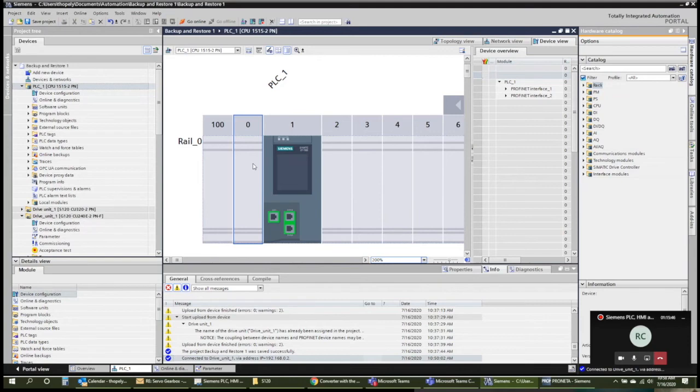If you're from the Rockwell world, hopefully you know that, but if you don't live in it every day or don't talk communications every day, you may see that and think it's interchangeable with the TCP IP that our computers use to get to Google or whatever. But they're actually different. Ethernet IP is very akin to Profinet in that it's intended to be a deterministic industrial protocol. So, sorry, a bit of a tangent there. Short answer is just go with Profinet. You'll save yourself a lot of time.